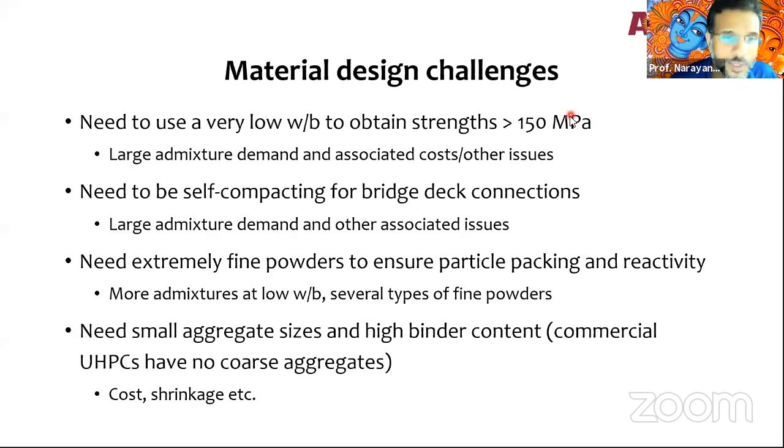But then I showed you in the last picture, I need my concrete to flow very well also, which is another conflicting requirement. To make sure that happens, I need to have a lot of admixtures. But admixtures don't really work without a certain amount of water to make sure that they can be carried everywhere in the mix. And that is where we typically come to a number of about 0.2. 0.18 to 0.2.